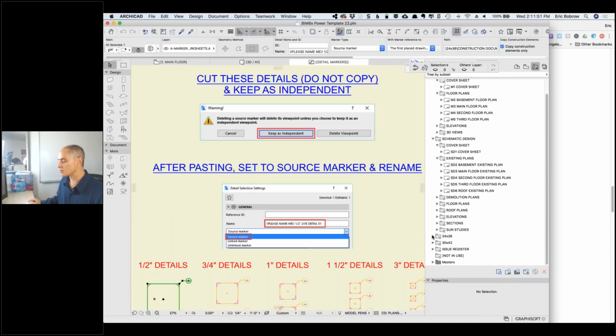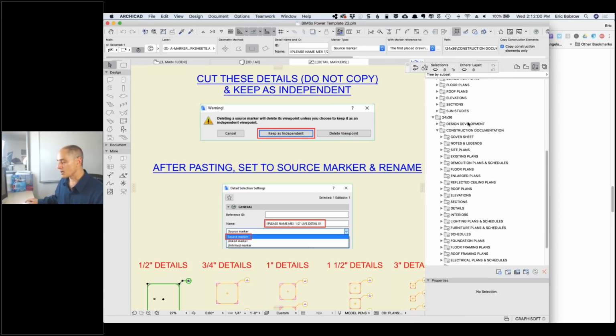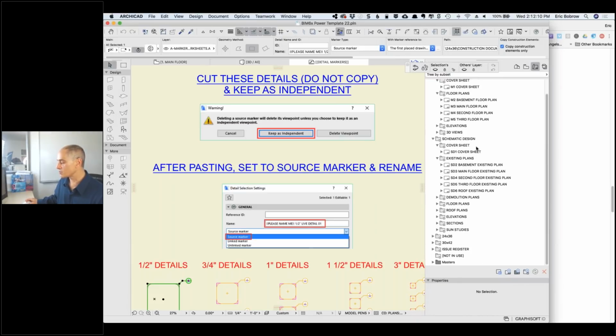It starts getting a little bit more. And as we get into the other sets, we've got design development and construction documents here, and each one of these has more. So we start having just a ton of different sheets set up for all of these things. And one of the things that they've done, which we've done in MasterTemplate as well, is to have a place where you say, I'm not using this. Instead of deleting it, you can just move it in there, and then you can exclude it from the list of sheets.